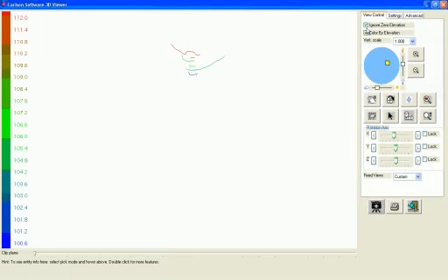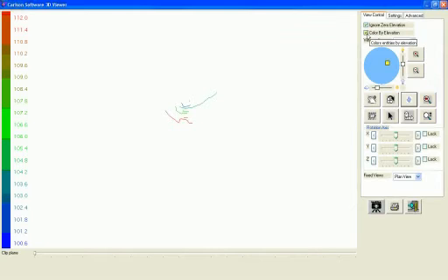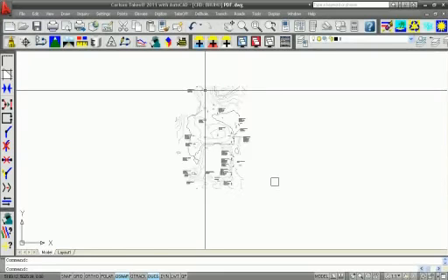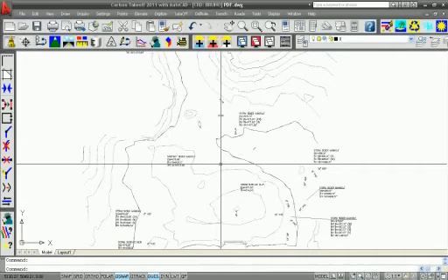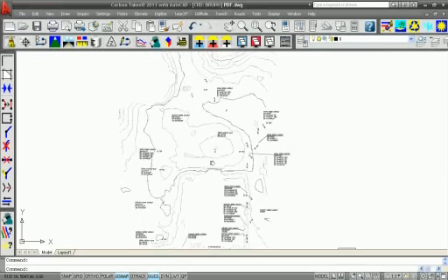okay, ignore 0 elevation. Let's see. Where's my line work here? I can see those contours that now have elevation. Yep. And just seeing if I could show all the contours. So, I've begun the process now of elevating some of the line work in here, which is a step closer to making a model for the existing data.